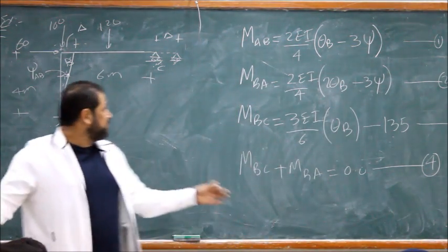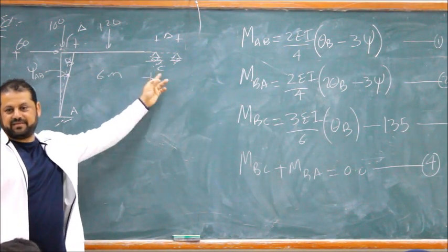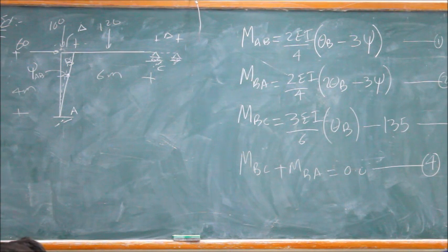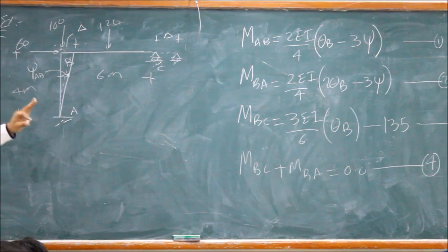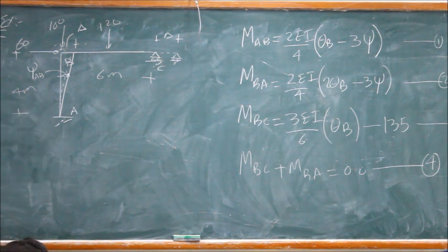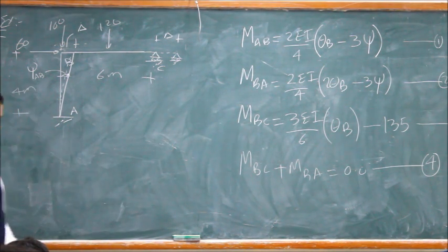MCB? If you do MCB, you will add theta C. You add one unknown and one equation, not so easy. Where do you get the equation in a sway frame? It's tricky. In a sway frame, where you get the fifth equation, the equation you need, is tricky.